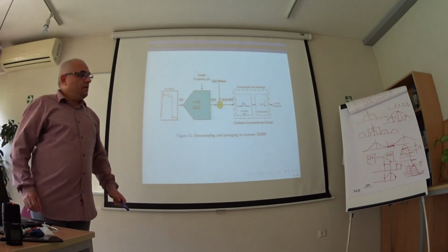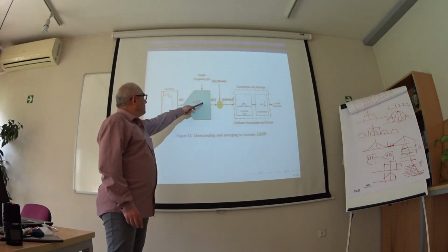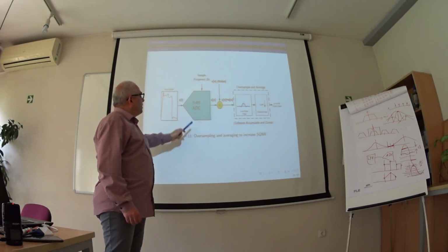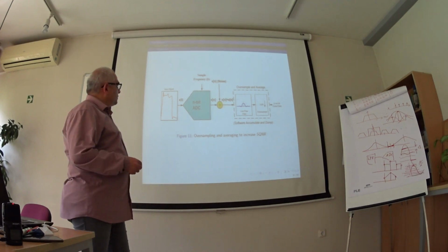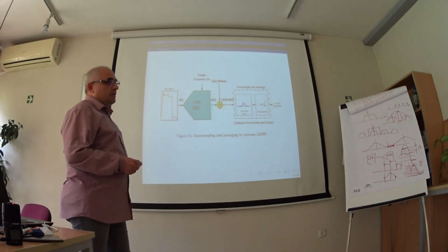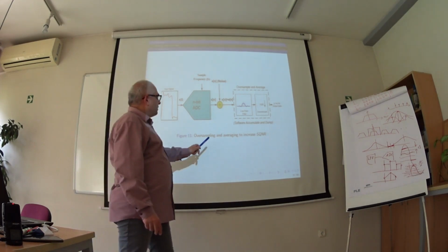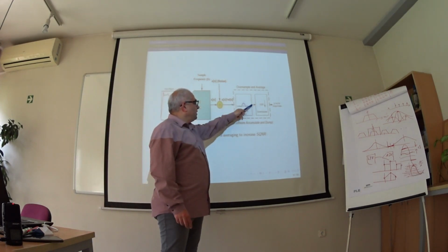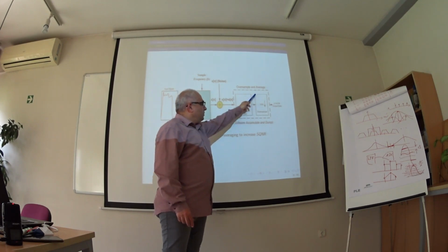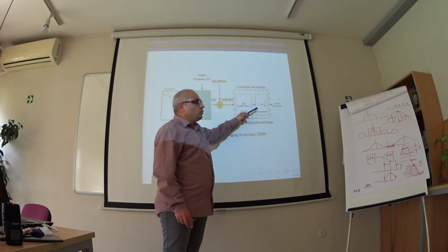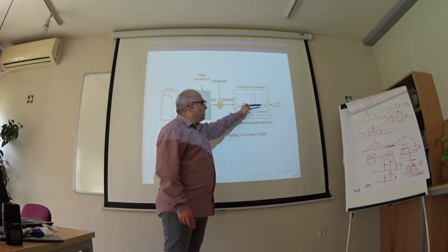Here is the idea. We have an n-bit analog to digital conversion. It works with a sampling rate much higher than necessary, and after that we have low pass filtering and downsampling, decreasing the sampling rate back to our requirements.